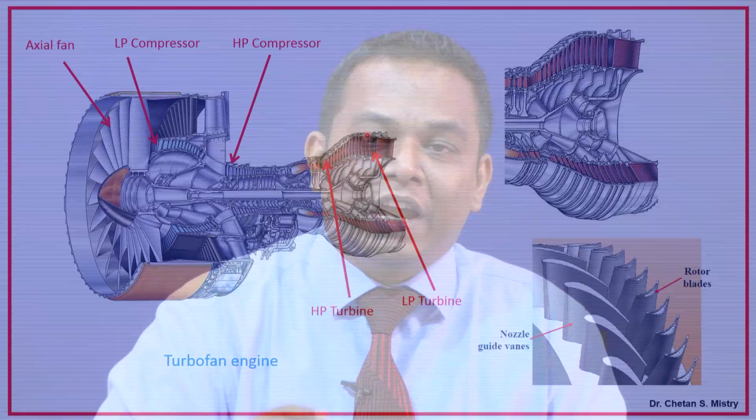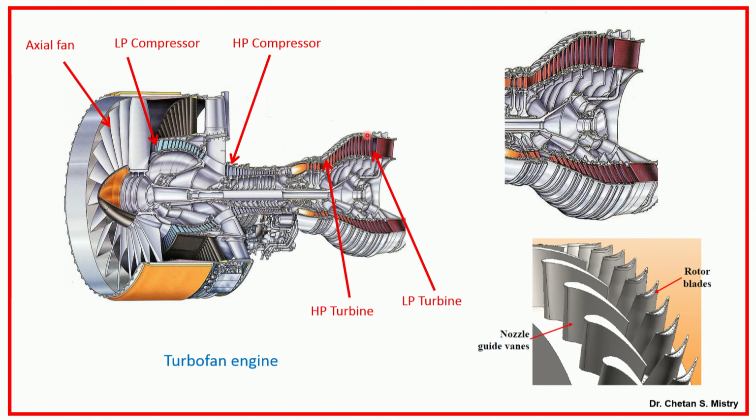Now moving downward, if you look at my blades, they are of high aspect ratio, or they are the taller blades. So if you look at here, this is my LP turbine blade. Now for this LP turbine, what is the speciality here? If we look at the aspect ratio, that is different. And if you compare in other sense, my axial chord, which is the distance from leading edge to trailing edge, is also less. And if we consider the HP configuration, we will have a chord that is slightly larger, okay, and the aspect ratio will be in the range of 1.